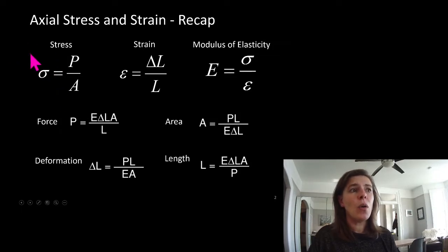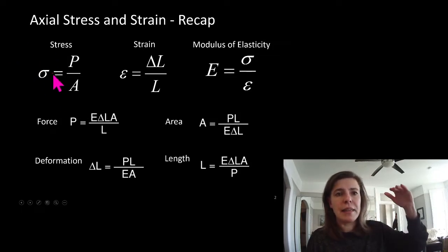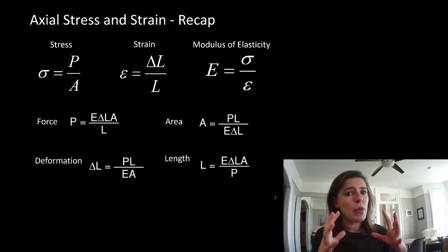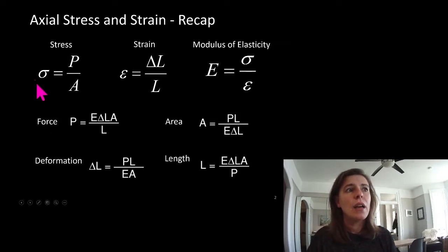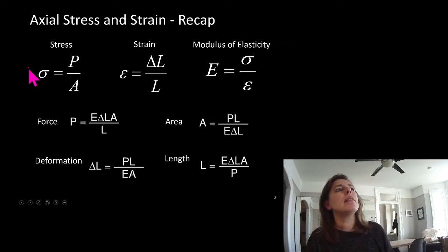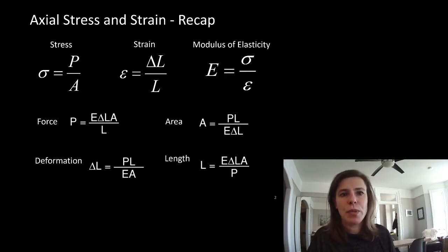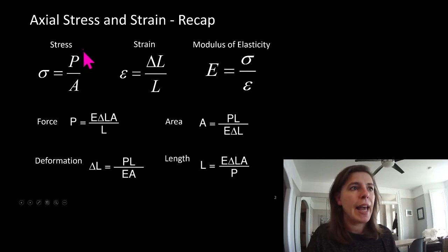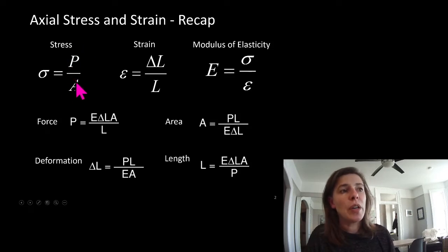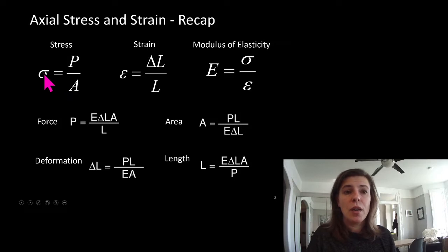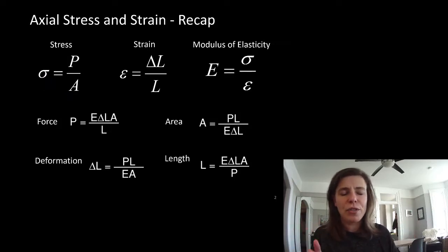And if we know that different materials have a different limit on the maximum amount of stress we can see, well, we should be able to say steel had a maximum stress of 350 MPa. And we knew our force and we knew our area, and the stress that that object was going to see was 349. Don't worry about reduction factors right now.